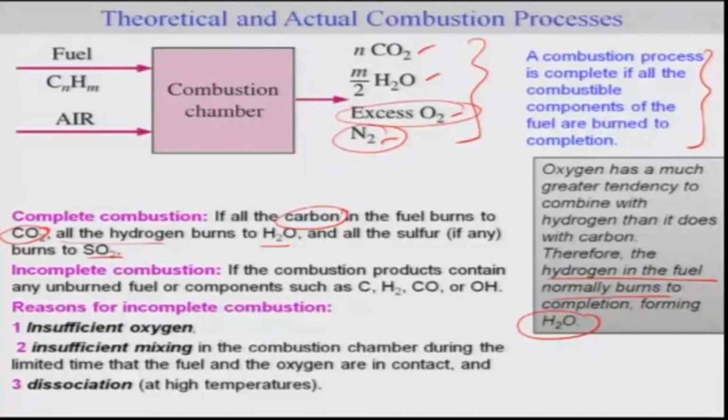Now if there is an incomplete combustion, then the combustion products contain components such as C, H2, CO and OH. So what are the reasons for incomplete combustion? Of course the first is that you don't have sufficient air or sufficient oxidizer, that means insufficient oxygen. Another possibility would be insufficient mixing in the combustion chamber, where fuel and oxygen are in contact for only a limited time. If you don't allow fuel and oxygen to have proper contact, the time is limited, hence it doesn't mix well and then it doesn't burn. So this is another possibility.